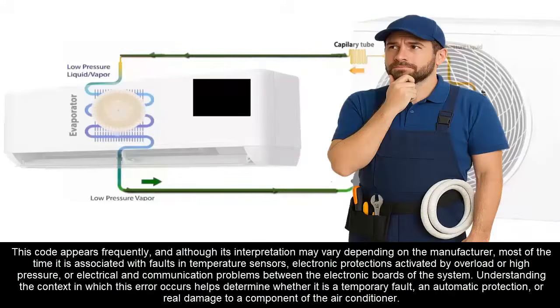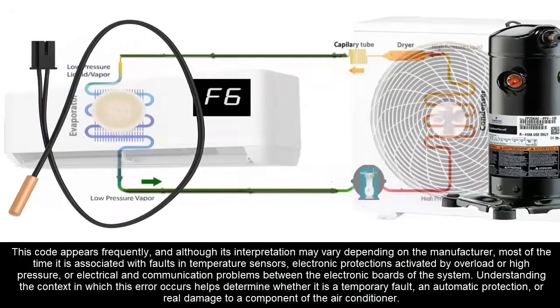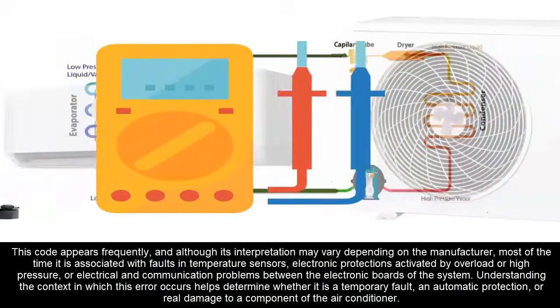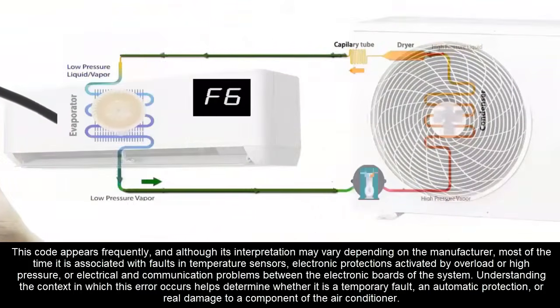This code appears frequently, and although its interpretation may vary depending on the manufacturer, most of the time it is associated with faults in temperature sensors, electronic protections activated by overload or high pressure, or electrical and communication problems between the electronic boards of the system. Understanding the context in which this error occurs helps determine whether it is a temporary fault, an automatic protection, or real damage to a component of the air conditioner.